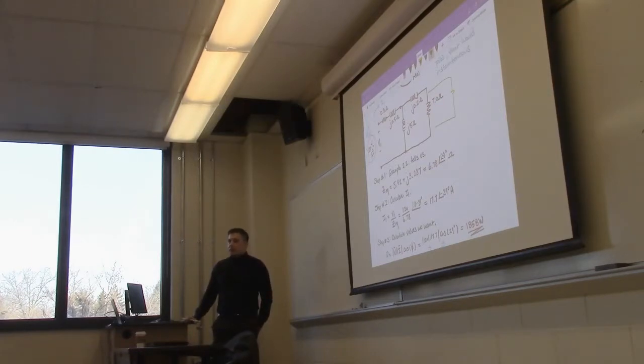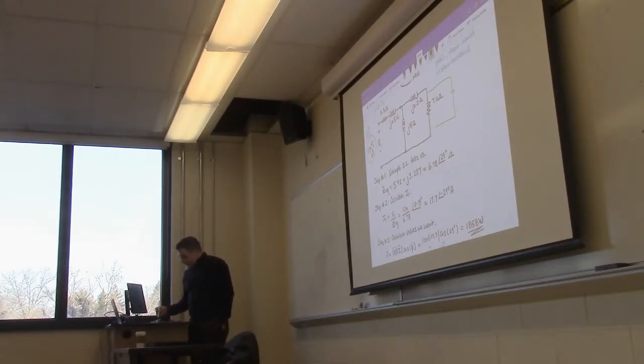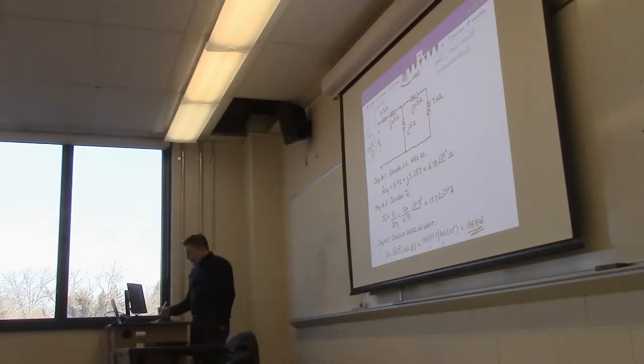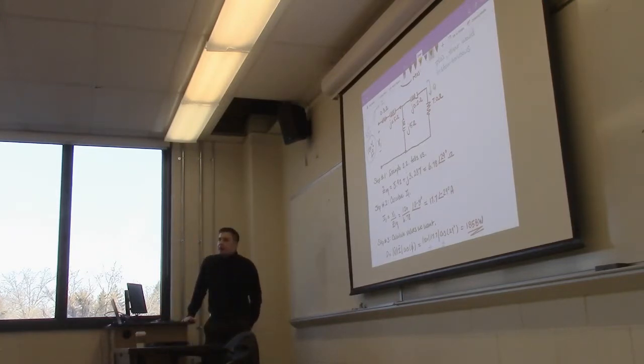So that's going to be an important part of the question, is also what is our target for the power factor correction. Now, why do we put it in parallel as opposed to series? That is sort of a practical question. As opposed to trying to give some sort of analogy, I think I'll just draw it. So you have a certain amount of Q that's flowing down this branch right here, okay?